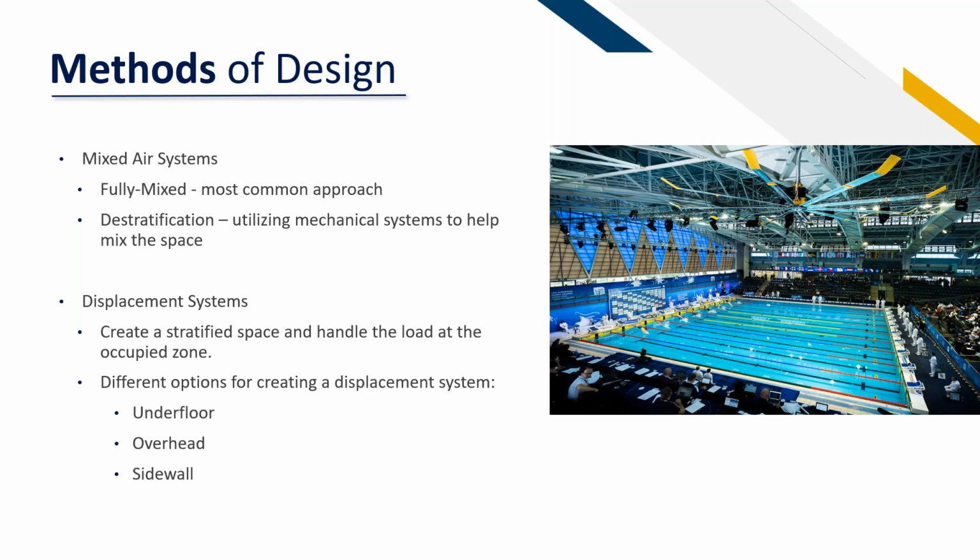So this is a low speed, low supply. You're supplying low on the ground. It's finding a heat source and it's rising up to the ceiling with a high return. So it's a single pass system, with much more ventilation effectiveness on that system as well, where you're delivering the air low and you're returning high. So it's kind of a single pass system. You're not mixing the space. You're actually encouraging a stratified space to induce that air to travel up to a high return.